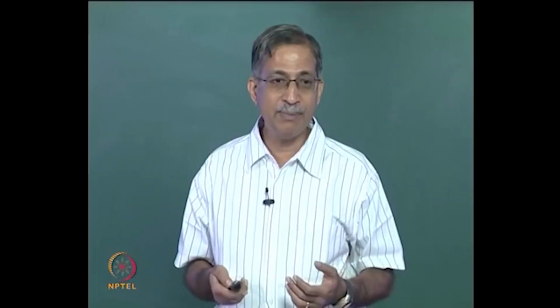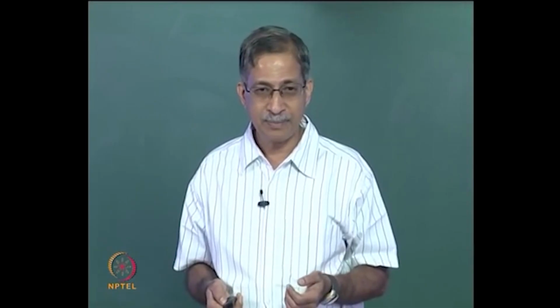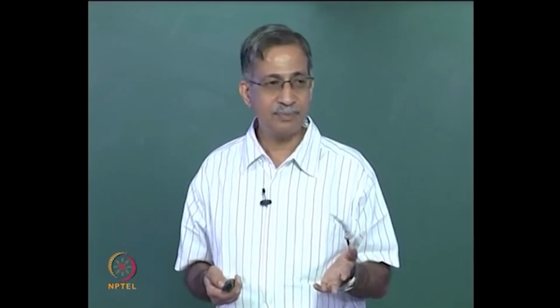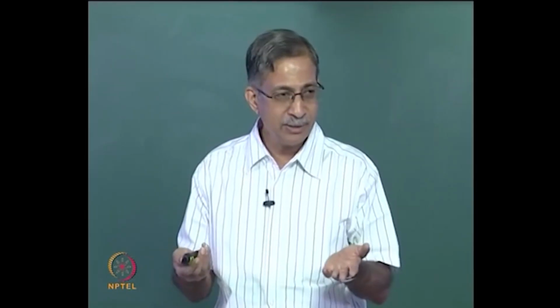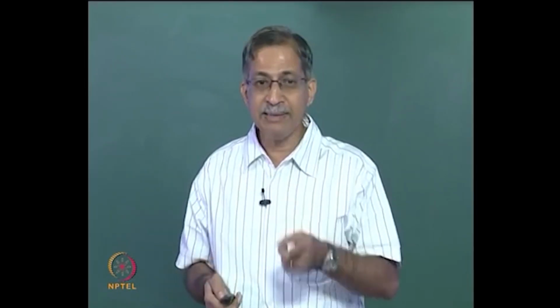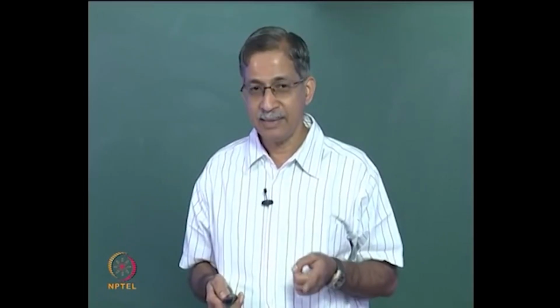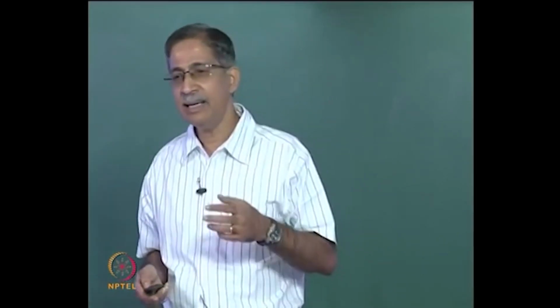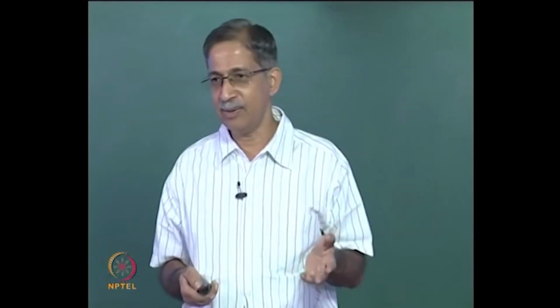These two you should be able to put on your primary structure. The direct forces are pretty easy to do. You can analyze this, can't you? And you have to find the deflections D1L, D2L, D3L. The L here stands for the external loading. Is it clear?